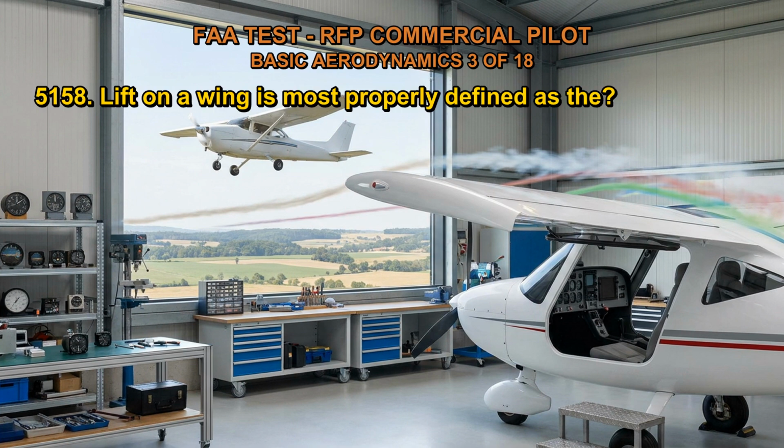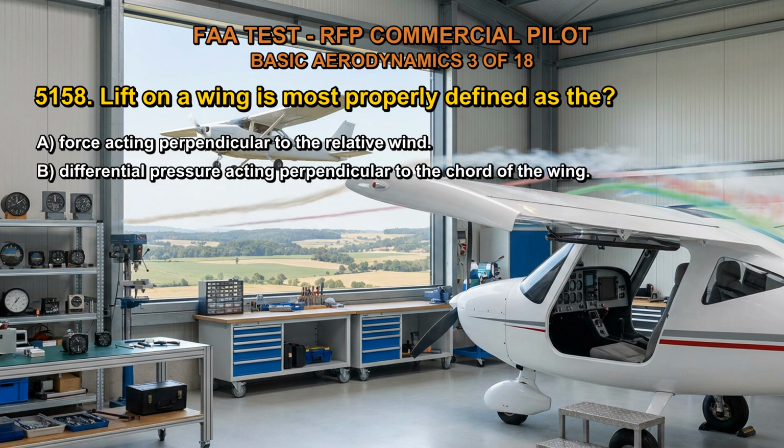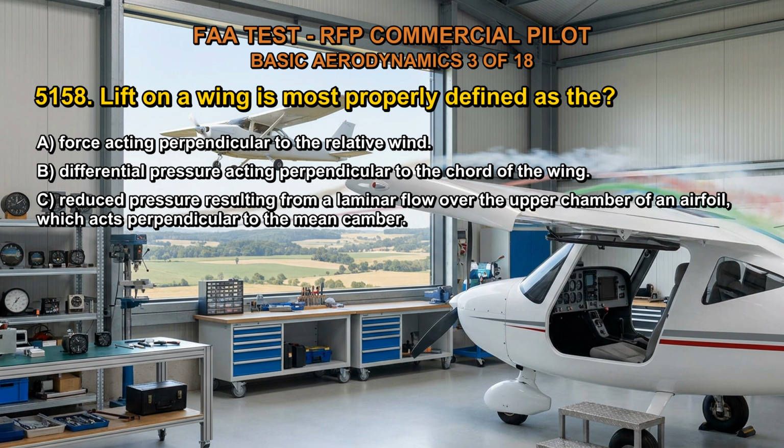5158. Lift on a wing is most properly defined as the A. Force acting perpendicular to the relative wind. B. Differential pressure acting perpendicular to the chord of the wing. C. Reduced pressure resulting from a laminar flow over the upper camber of an airfoil, which acts perpendicular to the mean camber. The correct answer is A.